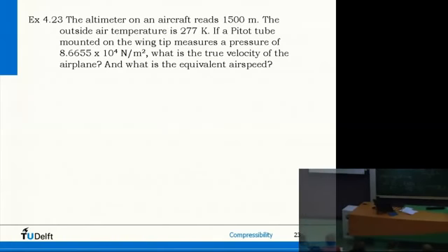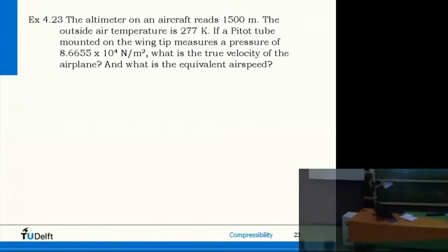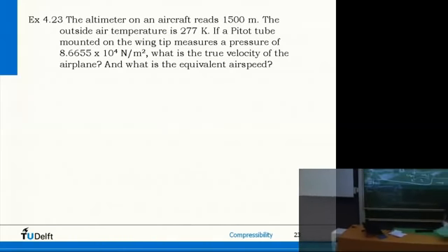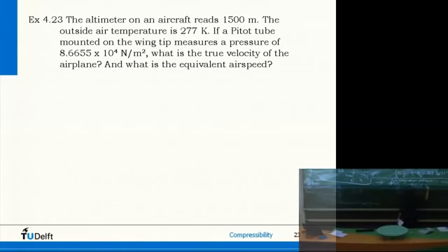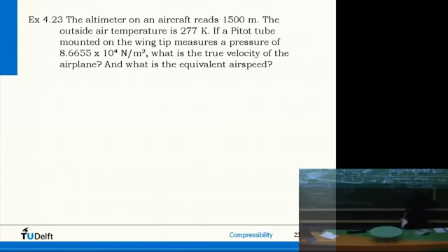The pitot tube just measures the static pressure or the difference between them both? No, the pitot, so question of the definitions, good point. Pitot tube always measures total pressure. So pitot tube is this one. Total pressure. This is the pitot static tube. So this one is called pitot static tube. So the pitot tube measures total pressures.